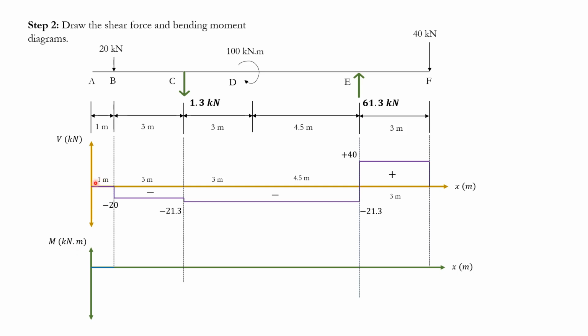At first, you have no area here. Remember that the area under the shear force diagram is the change in moment. So anything here or any concentrated moments here? No, nothing. So the area under this is 0, so the moment is 0. And at point B, there's shear, so there's area under the shear force diagram. That means there's a change in the bending moment diagram.